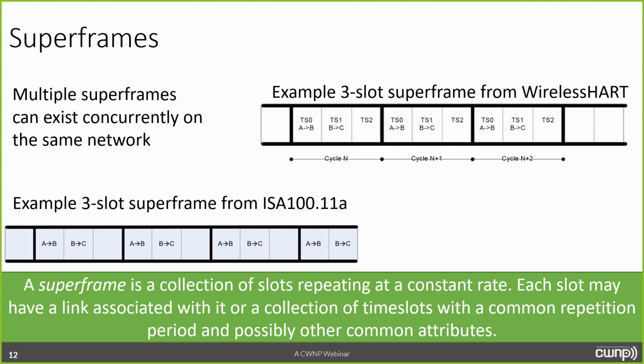And you can, of course, look at the spec, calculate any kind of microseconds that you might want to calculate or something. But a time slot always allows at least a frame and an acknowledgement if no collision occurs, because it's a shared slot, for example. So 802.15.4 frames are never any larger than 127 bytes. Therefore, a time slot is enough time to send 127 bytes in an acknowledgement. It's really that simple.